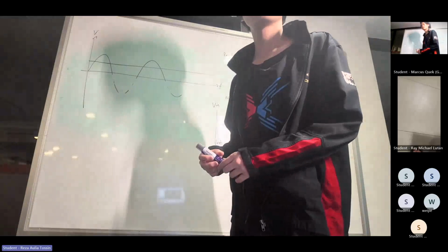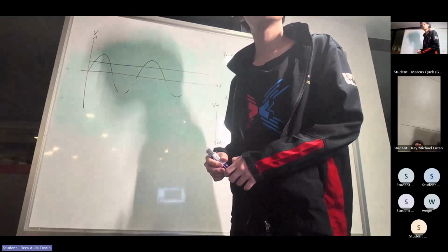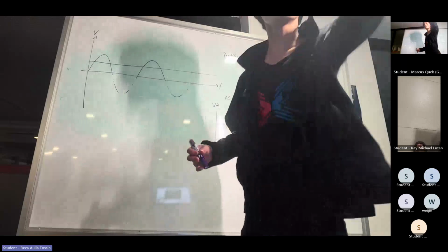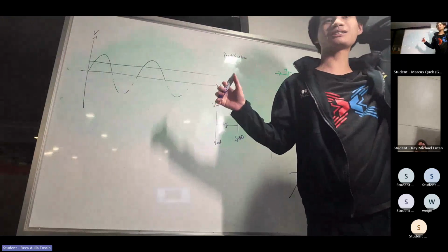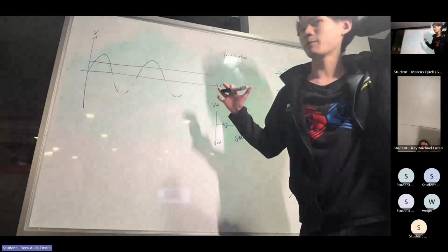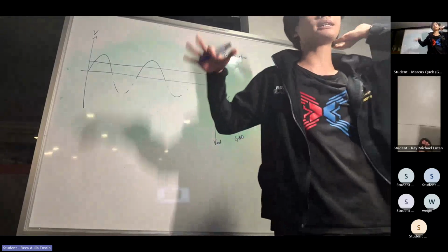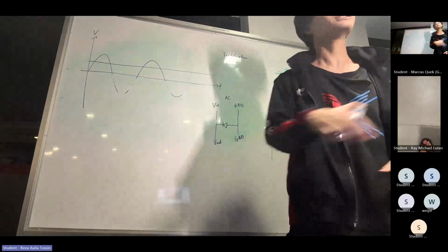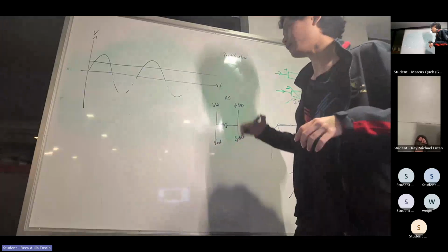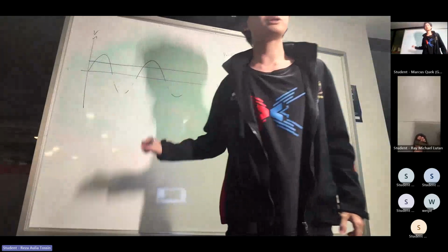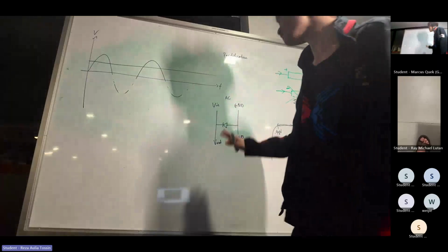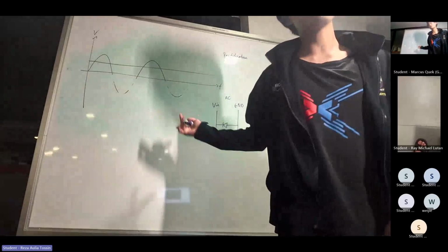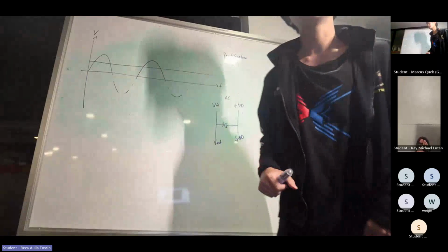There's a small voltage drop, but with an ideal diode, no. Everything we're talking about, by the way, is ideal components. We'll dive deeper into how components don't exactly behave the way you expect in the next lesson, including diodes, if I remember correctly. Anyway, we lose half the wave, so we're losing half the energy just to the diode. This is half wave rectification. It's very easy, just one diode, but it's not efficient because we're losing half our energy.